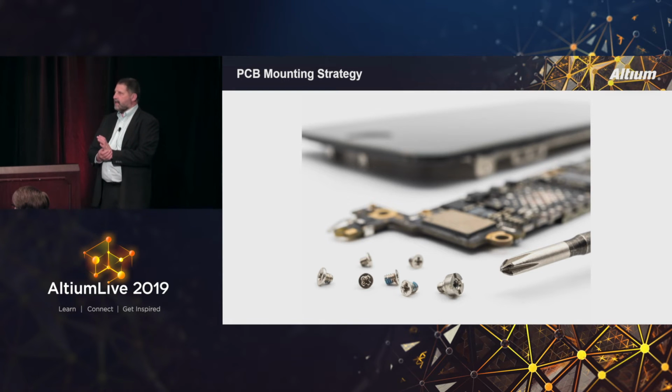You have a variety of different methods of securing that board, so oftentimes that's going to really help you package a product better. There's also pin staking, where you might have a pin protrude through the board, and you've got a surface mount connection that's going to tie into that stake. So there's a lot of really creative hardware out there now. Just be aware of that.